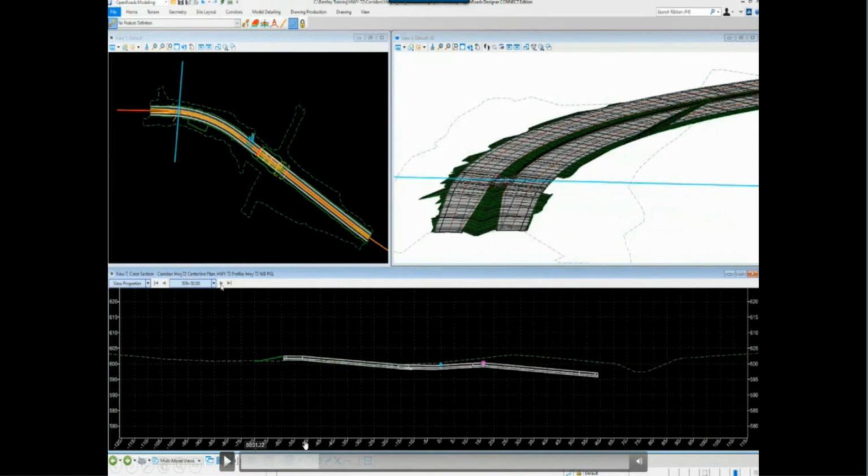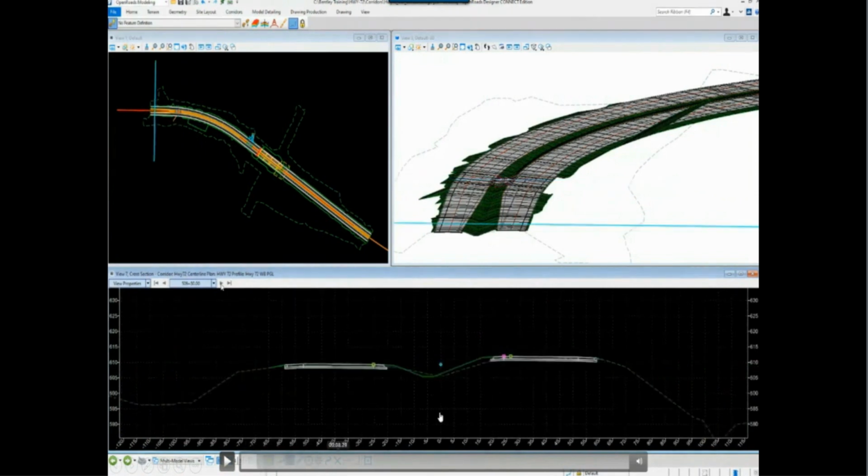Now, if we go back to the beginning of the roadway, as we look into that transition, you'll notice, again, we're going to have to modify the vertical between the eastbound and the westbound sides of the roadway. So we'll have to, again, create that control line vertically. But you'll notice the PGL that we're going to create is in line with the eastbound roadway.